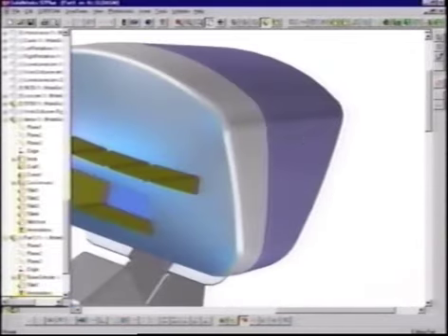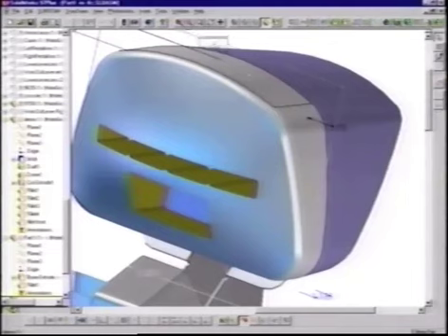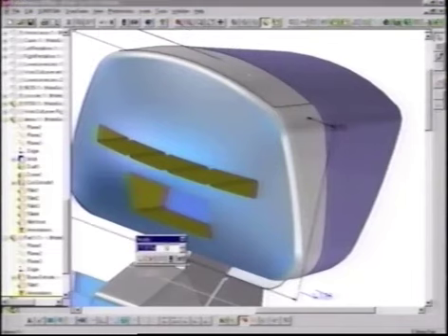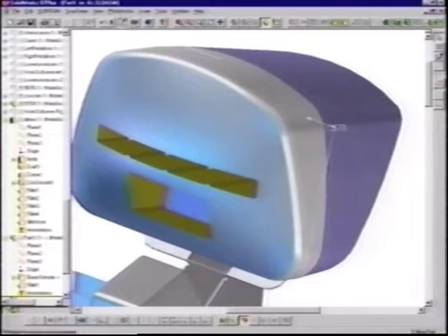And again, let's take a look at the benefits of the top-down assembly design that's available to us. Joe's going to go back and he's going to modify the width of this console display. Right now in the assembly, we're working in inches, but you know what? We know the width should be 375 millimeters. This is a minor point, but just something to make things a little bit easier for the user. He was able to type in 375 mm, and SOLIDWORKS does the conversion for him. When he says update, watch what happens to the front console and the back.